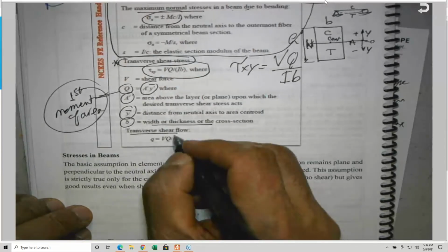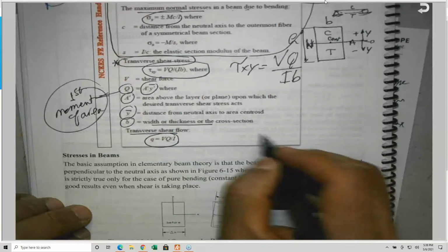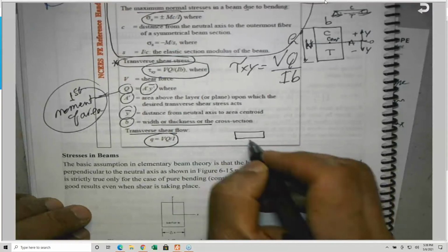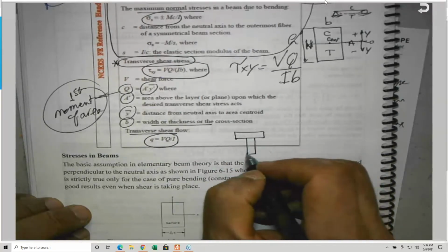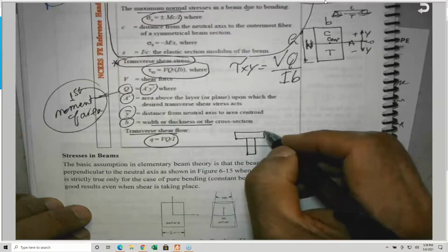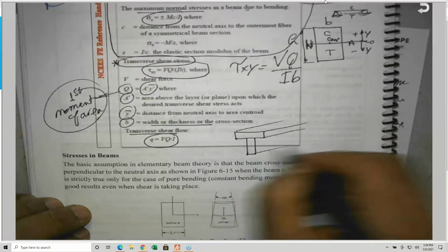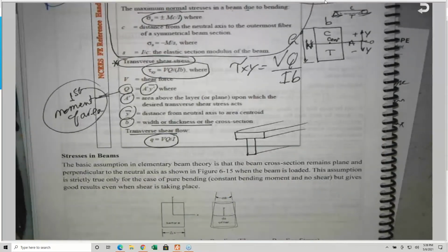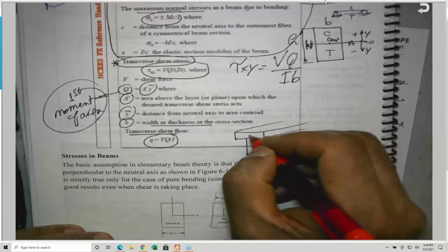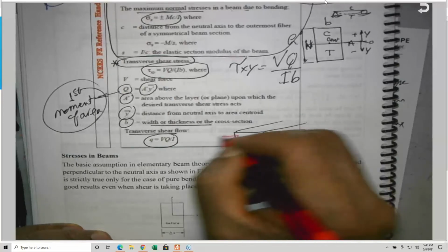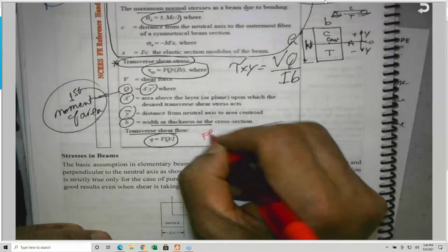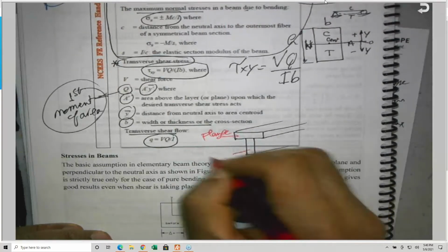And this is the equation that we use, by the way, when we are putting in nails. I'm sure in CE 121 you should know that. We cover this. So I have two pieces. This is what we do also in seismic design for diaphragms. I need to nail the upper portion, which is the plywood or the sheathing, in our case here the flange, and we'll call this the web.